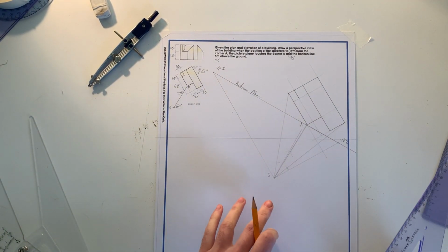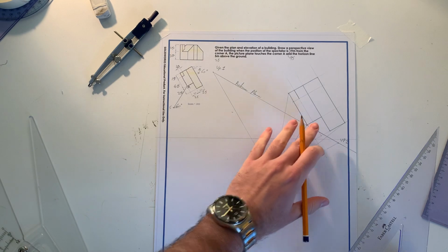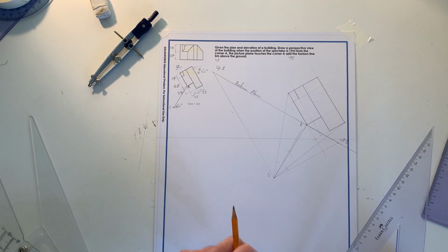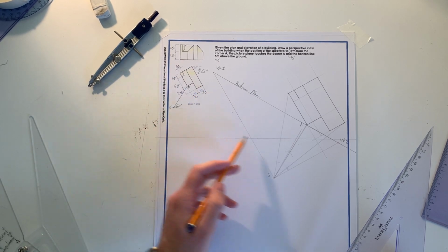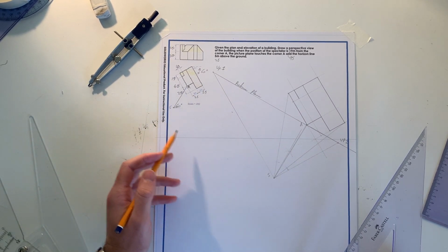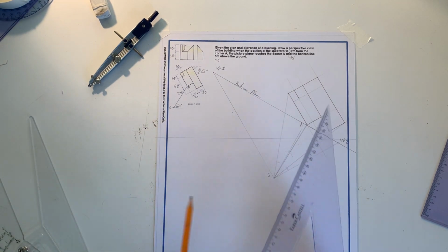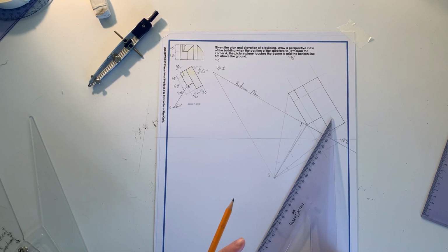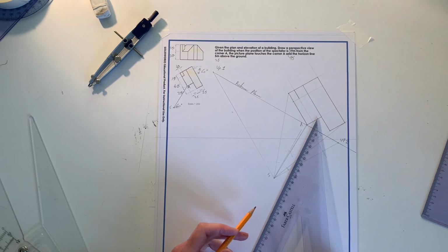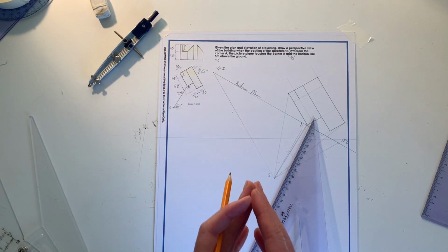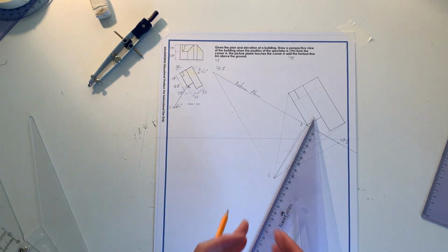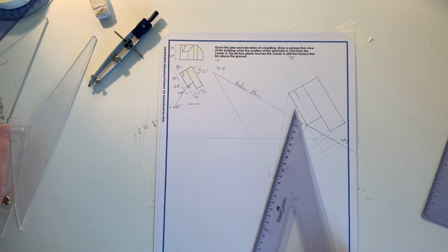Now what we can do is draw our ground line, which the object is going to be sitting on, as well as our horizontal line or horizon line, where our VP1 and VP2 will be located, where all the lines will disappear off to. So it's where the parallel lines will all converge. Now I know traditionally parallel lines don't converge, but in a perspective drawing, these lines are, by definition, parallel, but because of the drawing it looks like they converge at a point, which is our vanishing point. So it's a line that's at infinity.